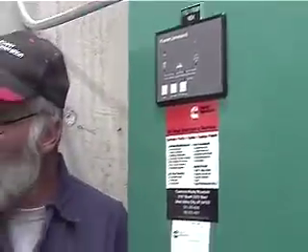Then you're going to call us and say, what's going on here? Usually the reason it fails to transfer is a micro switch problem. It happens once in a while, not very often. Usually it's because of construction dirt, because like you saw inside the bottom of the door, there was construction dirt inside there. So it's usually right in the beginning, usually within the first month or so after startup, because there's still a lot of construction going on. And so there'll be dust that ends up getting inside of the micro switch. And there's 4 micro switches up here, 4 micro switches down here inside the main contactor.